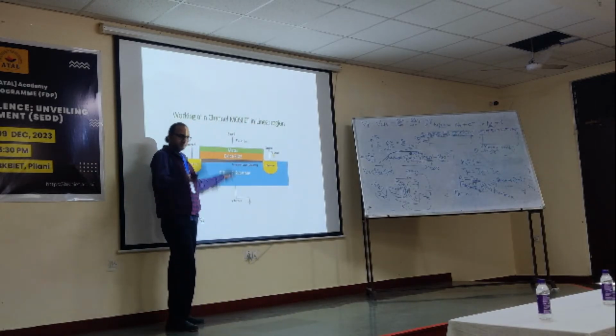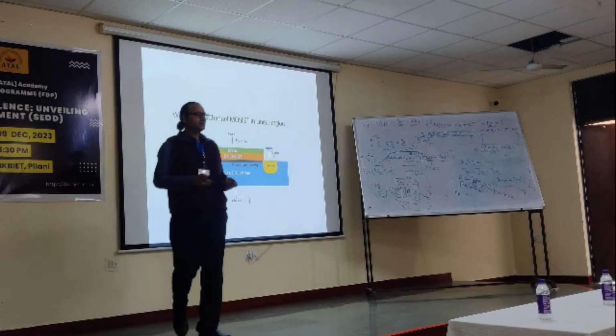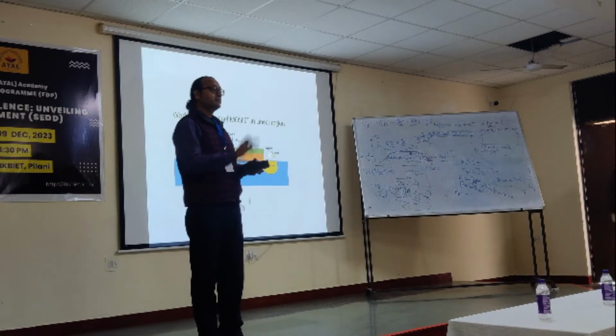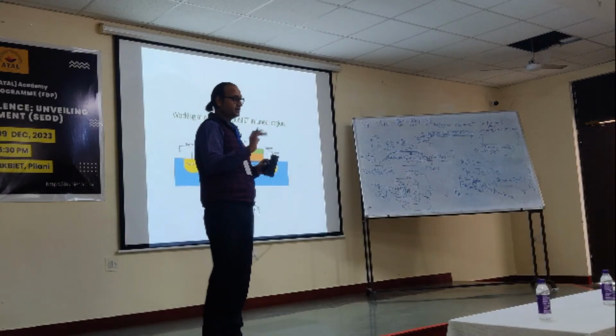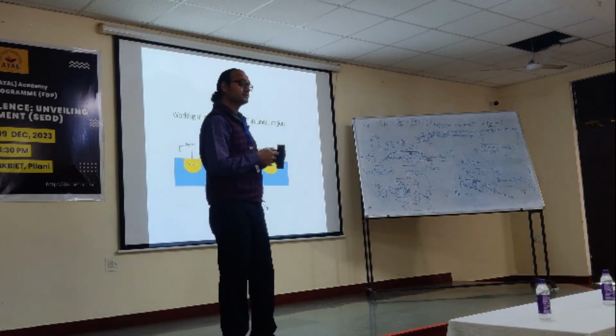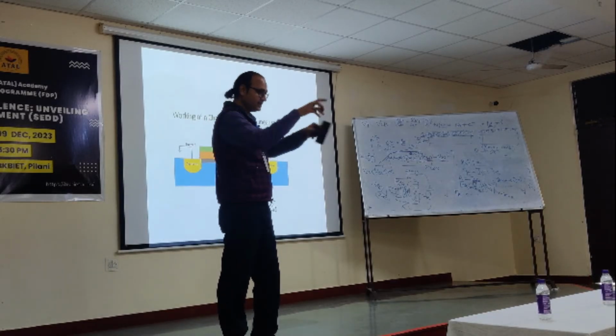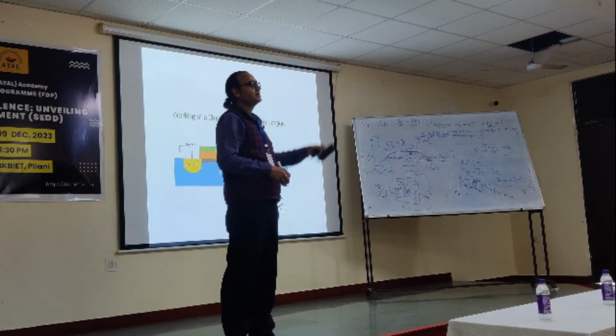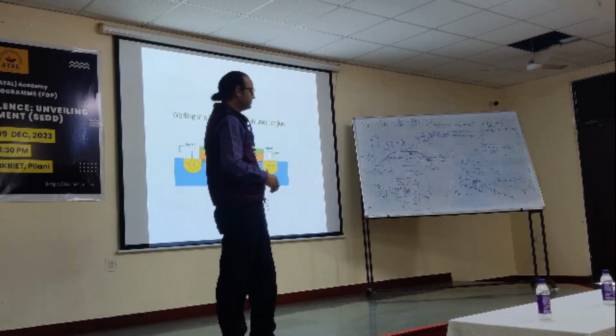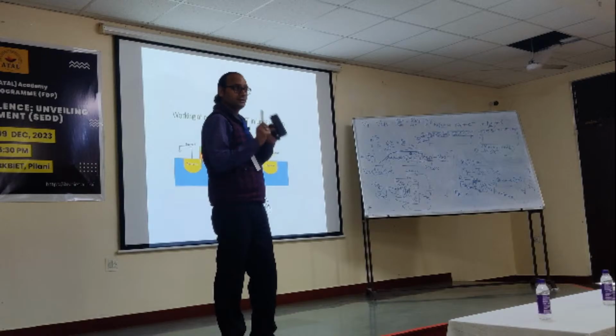Generally people say that MOSFET is simpler as compared to BJT. In BJT there are complications, but there are trade-offs. BJT is faster as compared to MOSFET, but MOSFET power consumption is small, MOSFET area requirement is small, and nowadays everything is done with MOSFET, but BJT is not completely gone.